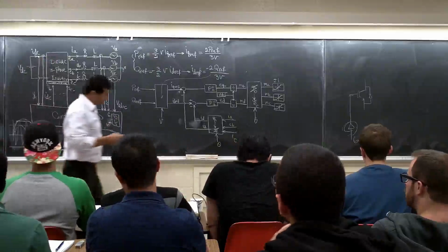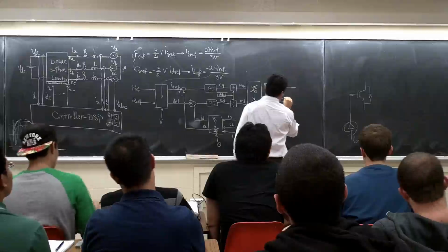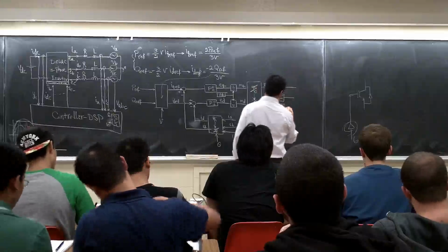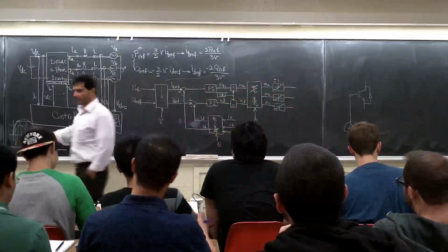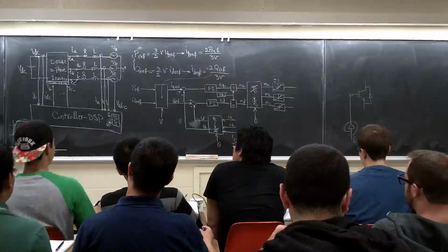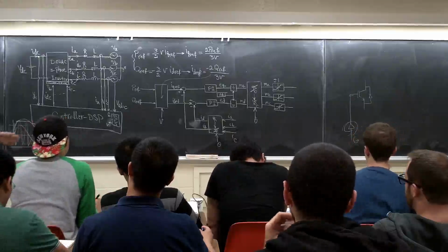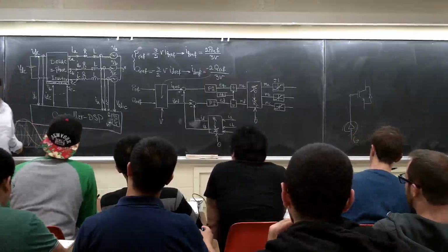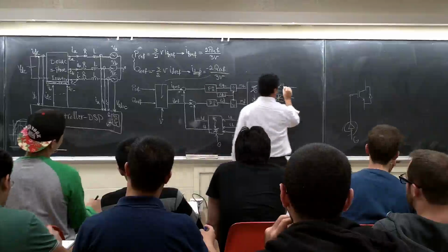Now, the next part. What do we do with the sine PWM to get my switching signals? I compare it with a triangular waveform, right? So I put this one here. I put a comparator here.